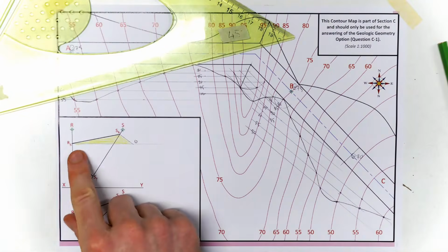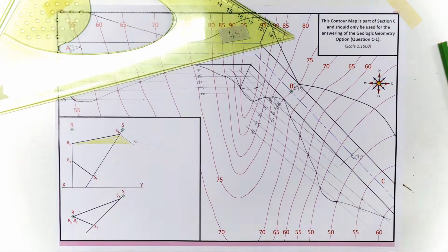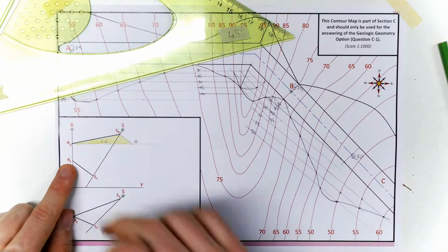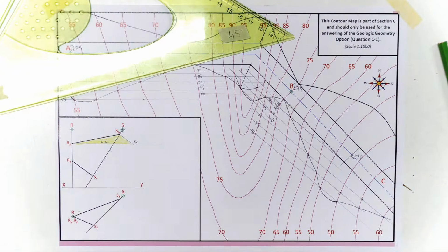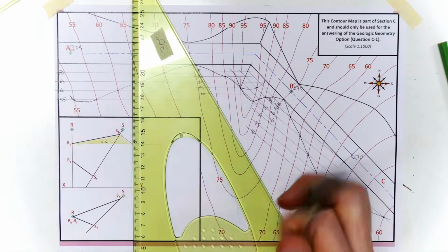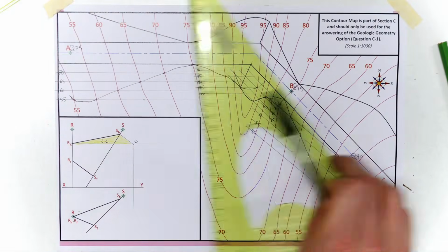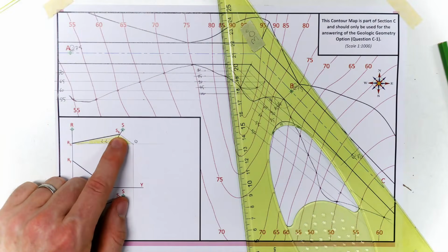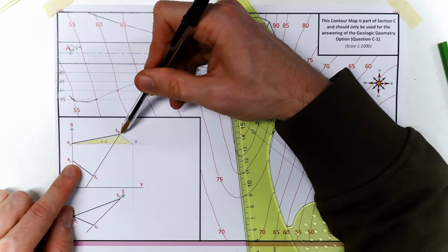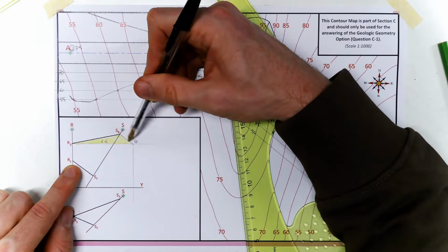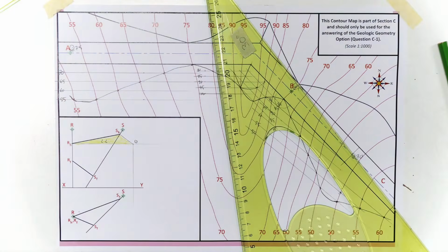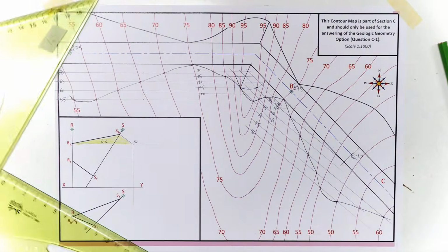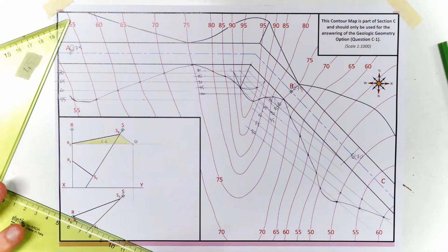Okay, so that level line, when we look down on top of it, because it's a horizontal line, we'll see it as a true length line here in plan. So O will be down here somewhere, and we know that parallel lines are parallel in all orthographic views. So this line here, which is parallel to RF, the foot wall line, we want to be parallel to it again.